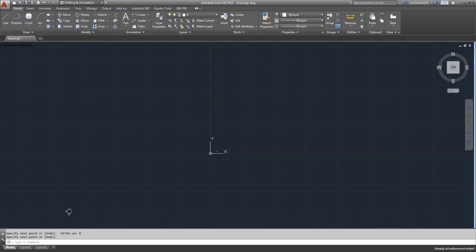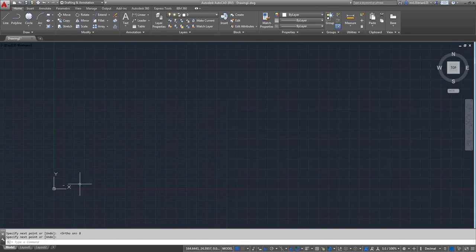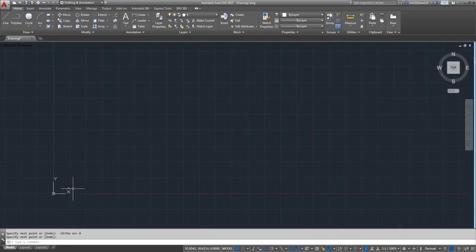Sometimes when you start using AutoCAD, and your units are in whatever unit you are using, I press like this and you will say, oh, it's not at the correct scale. That's not a problem. You should scroll over the line and you will see the real size. If you are looking at the grid, you can go right over here and press, and there's no more grid, or change the scale of the grid by pressing here at the grid and changing the distance.